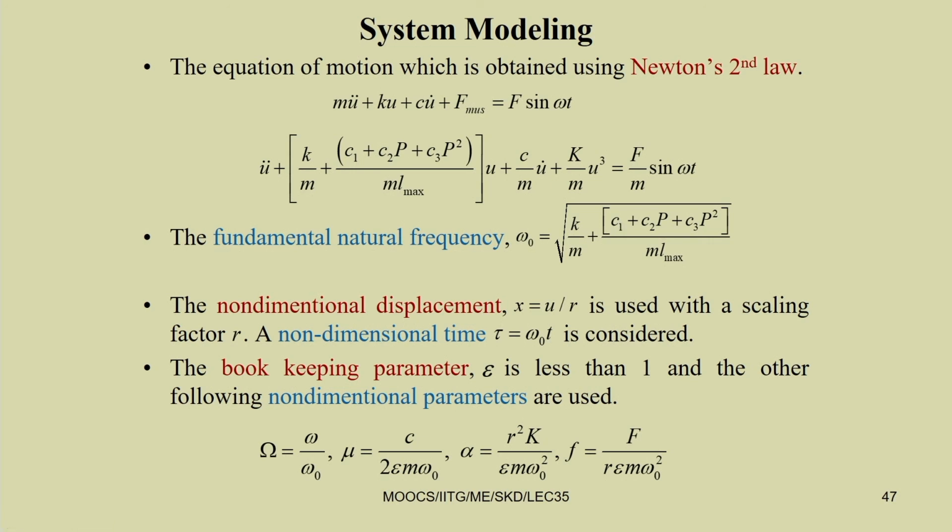In this artificial muscle case we require the displacement to be more, so that it can take more load or displace it more. So, we have to operate near the resonance condition, changing the value of omega 0 by actively changing the pressure which we supply from outside, and we can control the motion of the system.